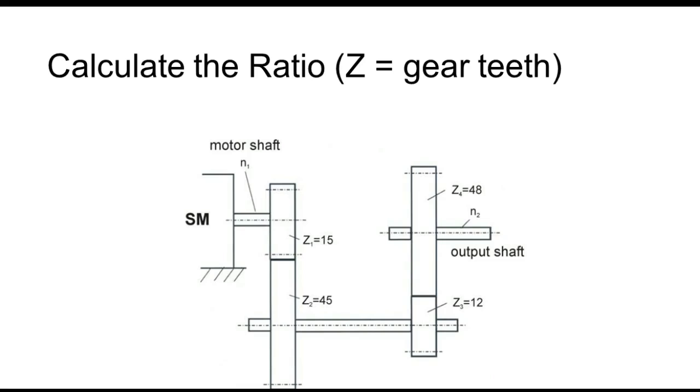And why do we do this? Well, when we start doing these gears, a lot of times this is very, very similar. So instead of having this gear turn this gear, we actually put gears on the same shaft, right? And the purpose of that is that the gear train or the gearbox will occupy less space. So we get a real good ratio between multiple gears instead of having one little tiny gear over here that's got 1 tooth for every 12 on my output, right? Does that make sense? So we see a lot of gear trains or gearboxes. Any questions on that? 1/12 or 12 to 1? Are we okay? Yes or no?